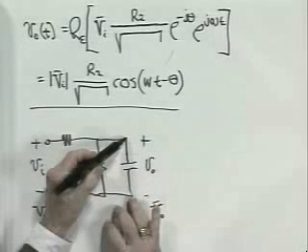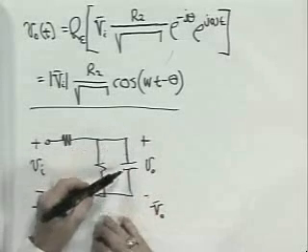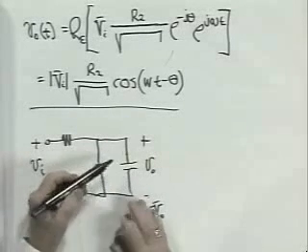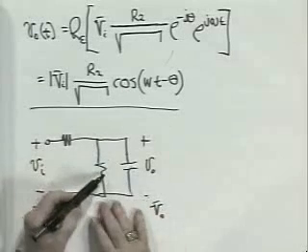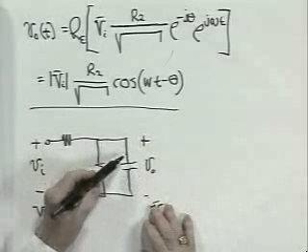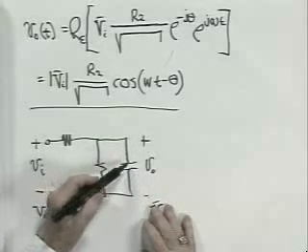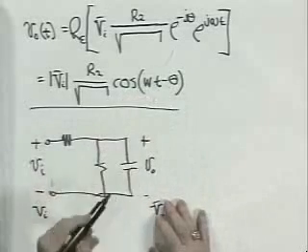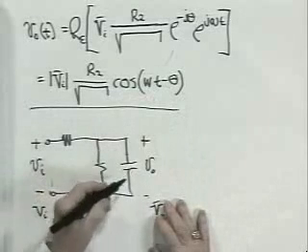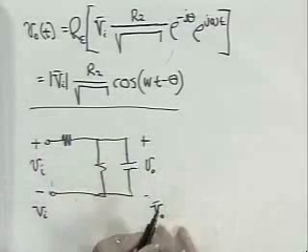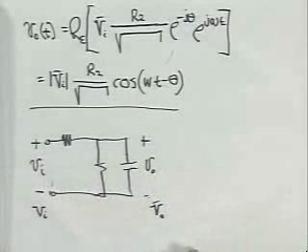The impedance of the capacitor varies as the reciprocal of the frequency, 1 over j omega C. So as I get to higher and higher frequencies, this impedance gets smaller and smaller and smaller until it dominates this parallel combination. And eventually this voltage vanishes because it is appearing across an element whose impedance is approaching 0. The pi over 2 that comes in the theta results from the fact that the impedance of this thing is 1 over j omega C, and the j shifts the voltage by 90 degrees. So the sanity checks appear to work out.